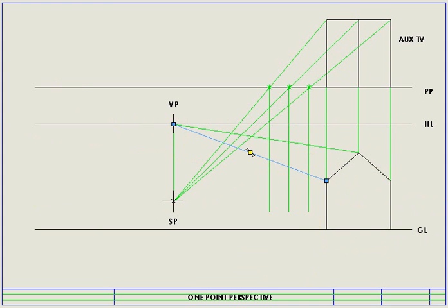Each one of these points in my front view will need to be connected. And already you can see that this building, if it was long enough, would eventually vanish onto the horizon line. Now the extra little bit of information that we would need when we look at the front view is the depth. How far back does this house or this building go? And we can only get that information from our top view. That's exactly why we projected each one of these points. That'll give us that depth.